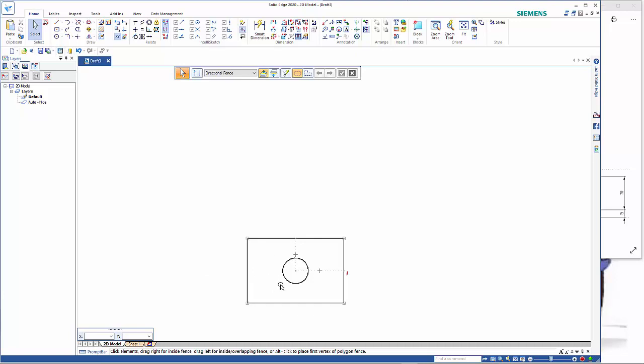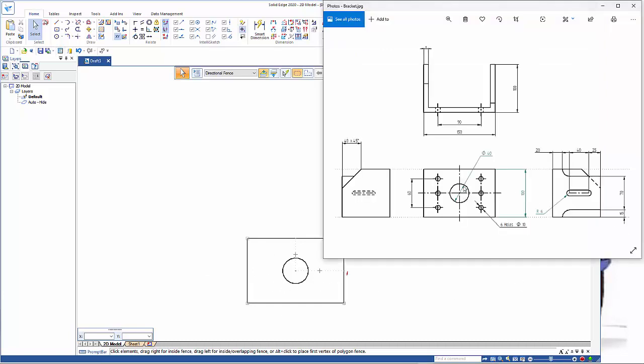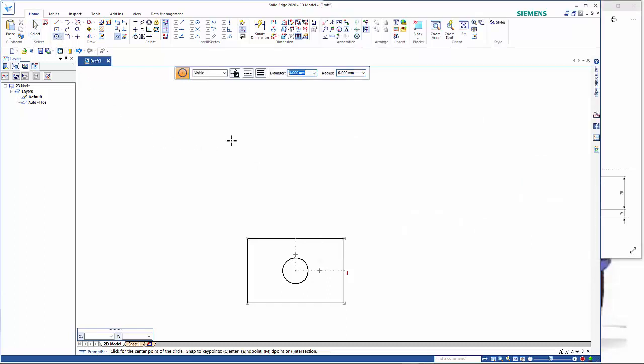I've also got 6 holes, which are 90 spaced and 60 down this way, and they're 10mm diameter. So click on here, 10 diameter, tab, and now I'm going to use my key in values. You can turn on your key in value down here with this one here, and I want to reposition the origin. So if I click on there and click on that point there, I can then start drawing it.